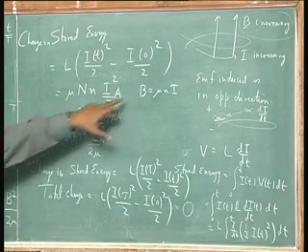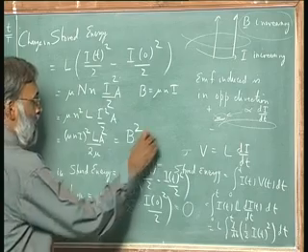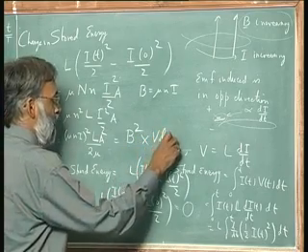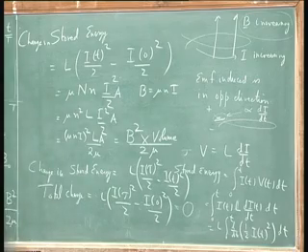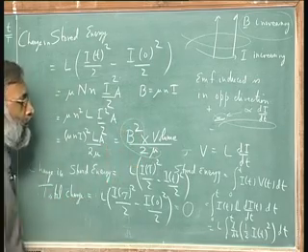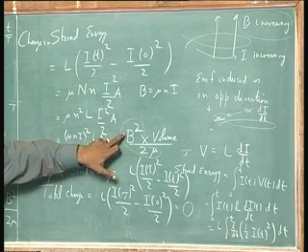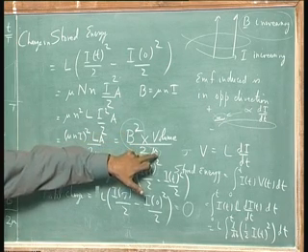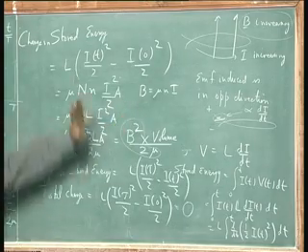This mu n I is B. So, it is equal to B squared times volume divided by 2 mu, and that is where we get back the same formula, that energy in the magnetic field is related to B squared over 2 mu. It is the same idea. The idea here we will come back to in mathematical terms, but the idea here is straightforward.